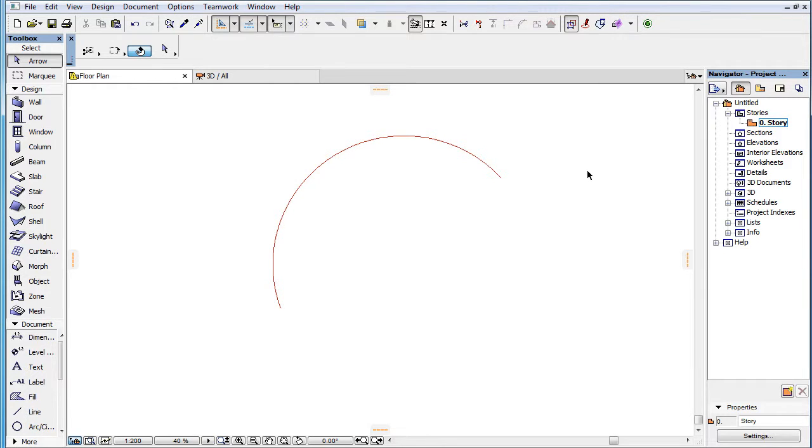This video clip presents why and how certain points and edges of elements are implicitly considered marked as snap references by Archicad 19. In addition to the user explicitly marking element points and edges as snap references, Archicad also implicitly considers certain points and edges of elements marked as snap reference. By doing this, the program can then intelligently offer temporary snap guides based on these implicitly marked snap references to help you in creating and editing elements.